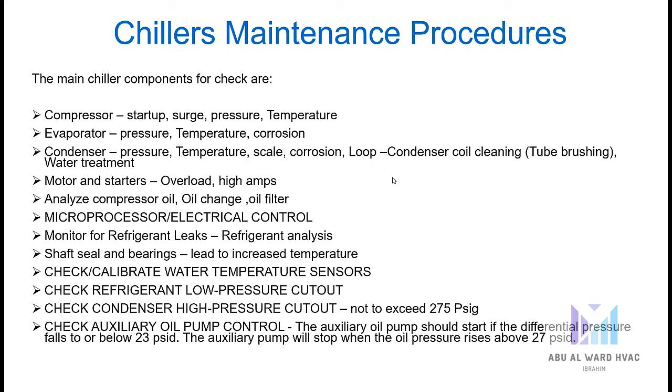The auxiliary oil pump should start if the differential pressure falls to or below 23 psid. The auxiliary pump will stop when the oil pressure rises above 27 psid.